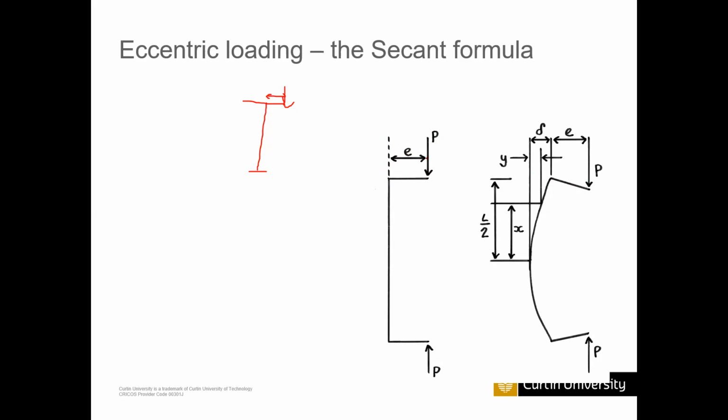So you can see this is a kind of eccentric load. With the eccentric load, you can see this kind of bending. Earlier it was only delta. If you apply the P load in here, you can see delta deflections. Now delta plus E as well, due to this eccentricity.